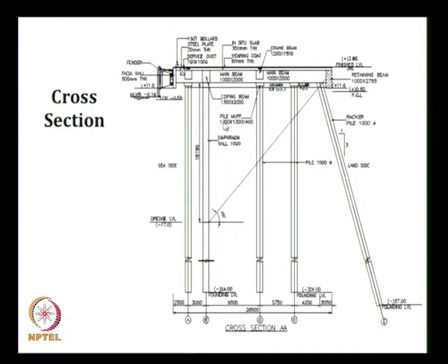There is a difference between transferring the load here and transferring the load here. If you transfer the earth pressure here, the diaphragm wall will be subjected to a lot of bending moment. Some portion of the pressure will go to the diaphragm wall in the passive zone, and some portion will be transferred as a shear at the diaphragm wall beam junction.